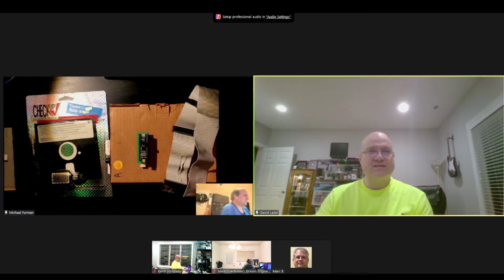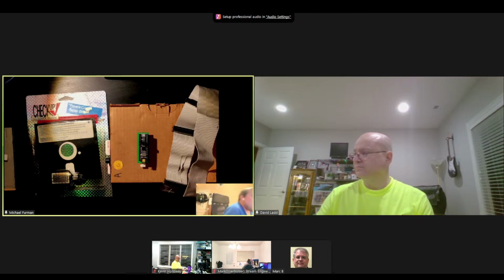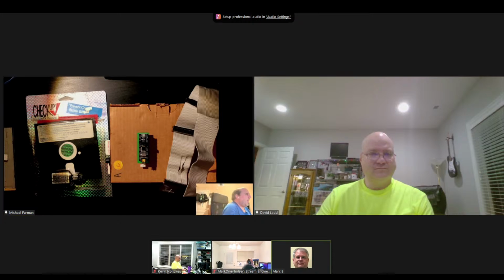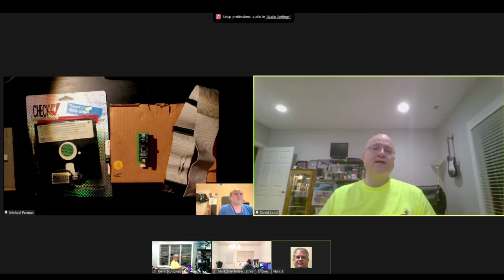The one that you gave me here is a little bit older. That's the STM32F103, I think. It sounds vaguely familiar. I don't know where my loupe is. So is it an open source project to build one? Yes, that one that Mikey's got, you can order your own PCBs, and the biggest problem that you're going to have with that model is finding a Blue Pill that doesn't have a fake STM32 chip.